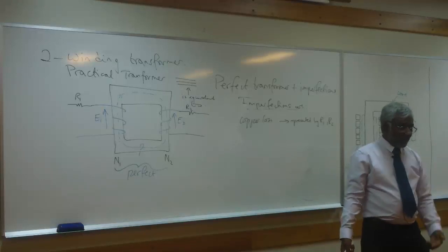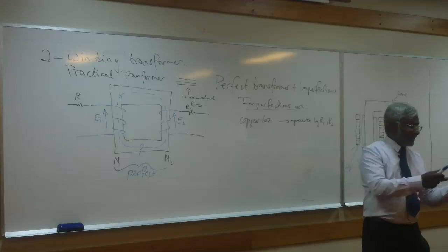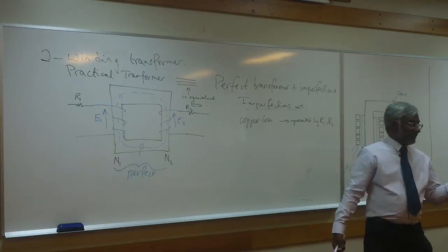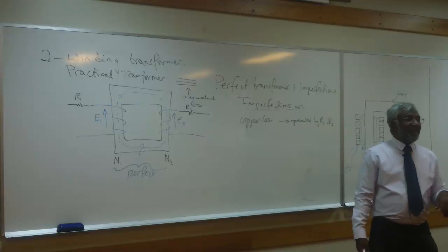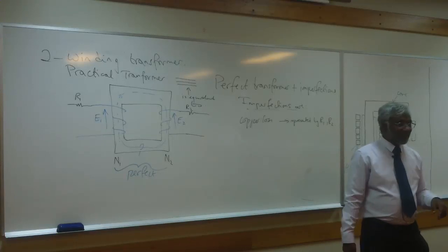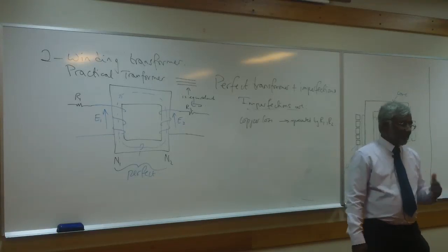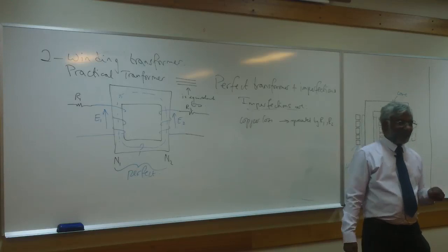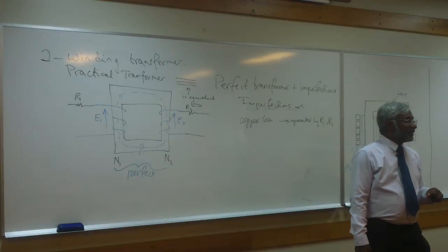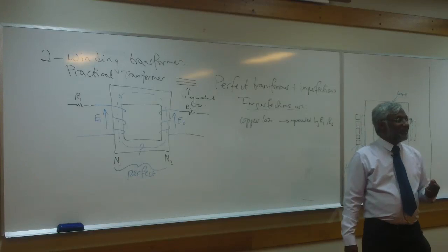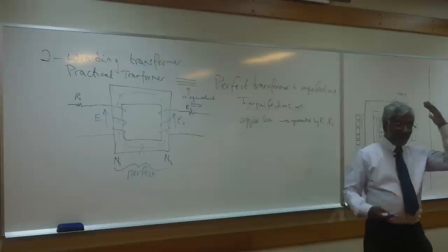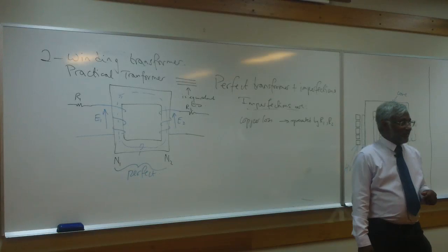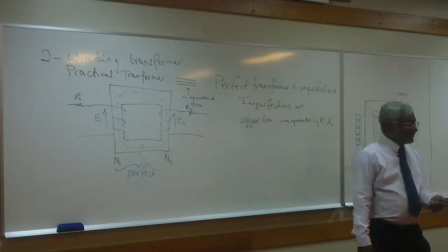From head to toe, it might be a bit higher. From this hand to that hand, it may be a bit smaller. And the problem there, of course, is that it goes through the heart region. So around about 1 kilo ohm is a good assumption. It can be a bit lower, many times it is a bit higher. That's why a lot of people escape: because they were dry and had not good connections, it was only 10 milliamps or 5.